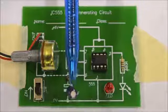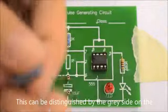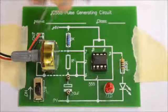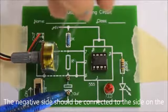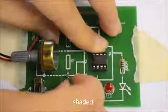the capacitor. Note that there is a negative side to the capacitor. This can be distinguished by the grey side on the capacitor or the shorter pin. The negative side should be connected to the side on the green circuit board where the capacitor symbol is shaded.